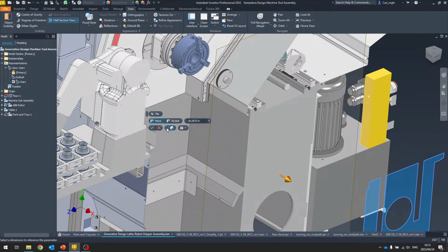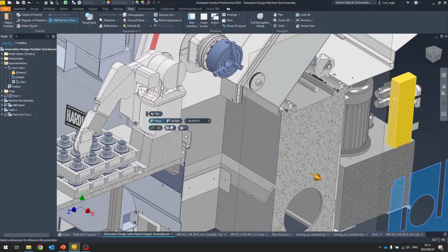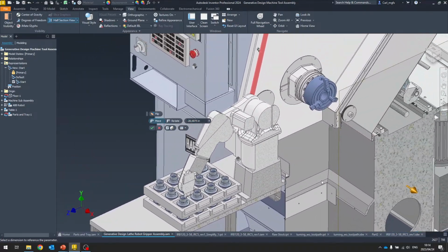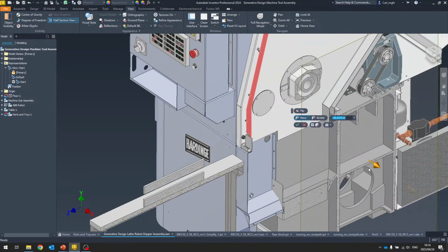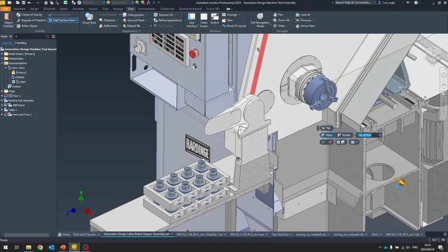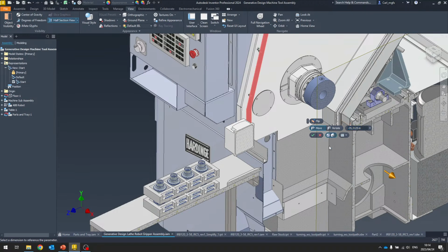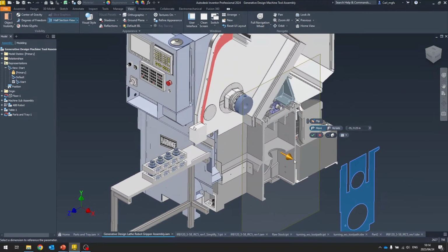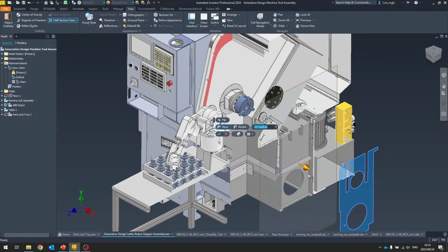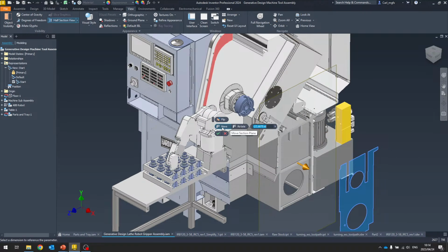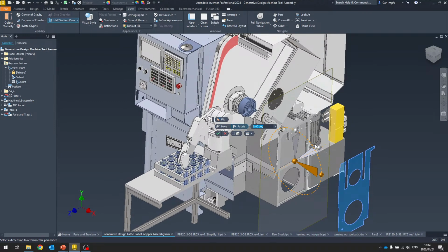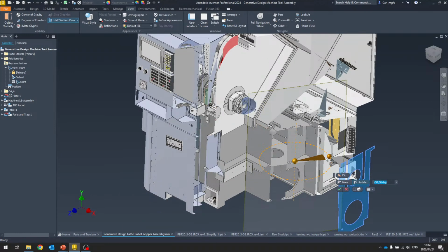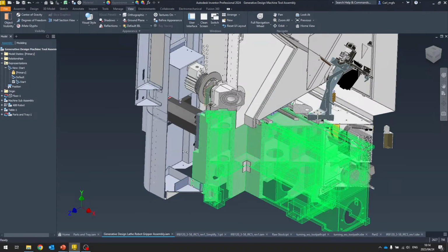And if we enable the end cap option, we will see we end up with that textured end cap. We can see quite nicely here in this robotic arm. And when we click and move, we'll see that the section is not as smooth when displaying that end cap. So I'm going to switch that off. Let's not display the end cap, and we are moving the section view back and forth, and we can also then rotate. So we're moving or translating it, but then when we enable rotate, we've got our 3 axes we can rotate around. And so I'm going to rotate this around, let's say minus 45 degrees, and accept.